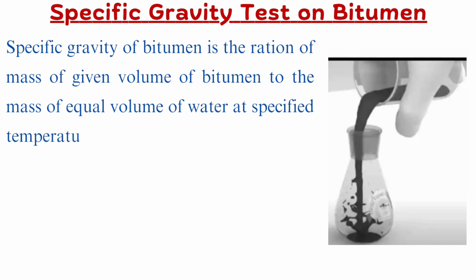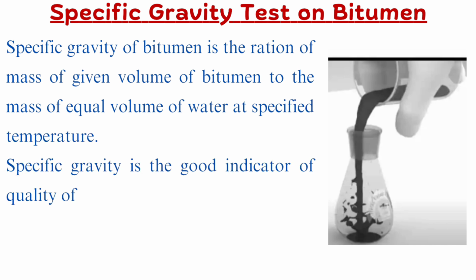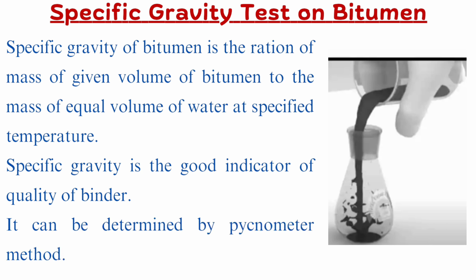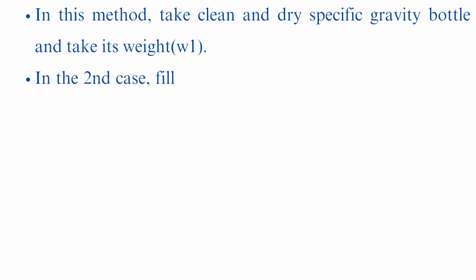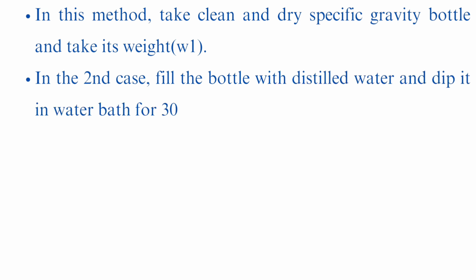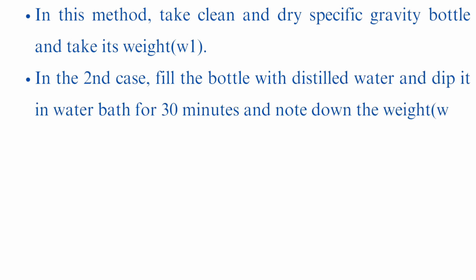Assemble the apparatus parts. Balls are arranged in guided position, that is on the top of the bitumen sample, and fill the beaker with boiled distilled water. Then apply temperature at 5 degrees centigrade per minute. At a certain temperature, bitumen softens and the ball slowly moves downwards and touches the bottom plate. This point is noted as softening point.